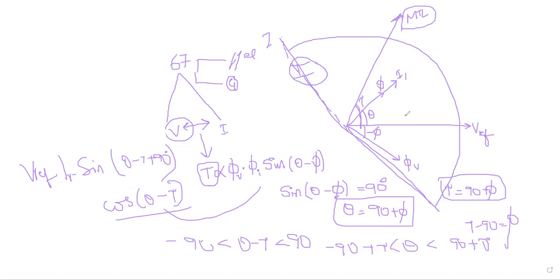Again, we have to mention the minimum current. What is the threshold current? And also, what is the minimum voltage to avoid the failures of the fuses or MCB trips? This may again lead to the chances of mal-operation of my directional overcurrent relay. So to avoid this, generally we will include that angle also.